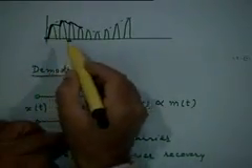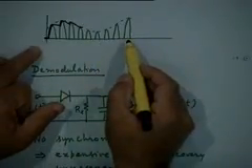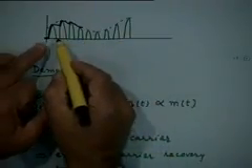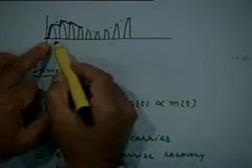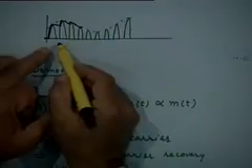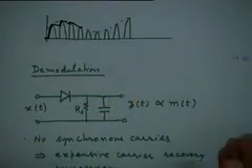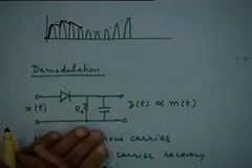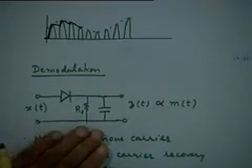And thereby you can see, of course this diagram is highly exaggerated in the sense that the carrier cycles will be much more closely spaced than I have shown in this diagram, right? So actually what you will see is not such a wavy envelope, but a fairly smooth envelope, which can be smoothened still further by a suitable low pass filter if required, right? So that's the basic principle.